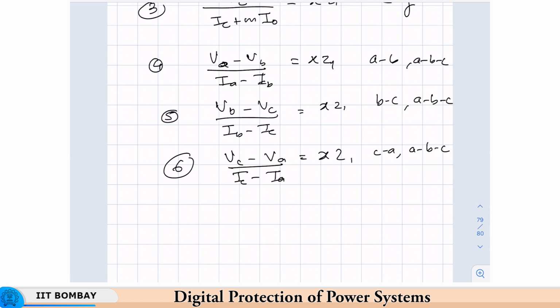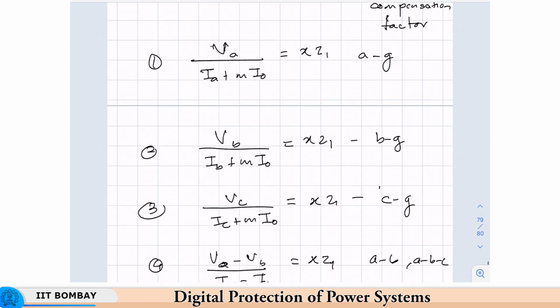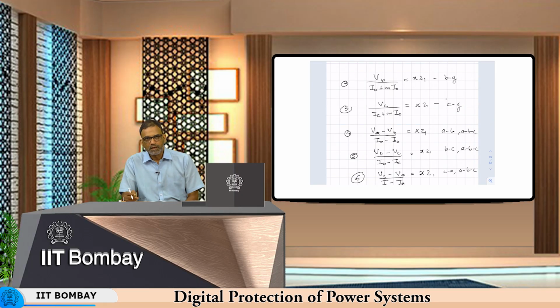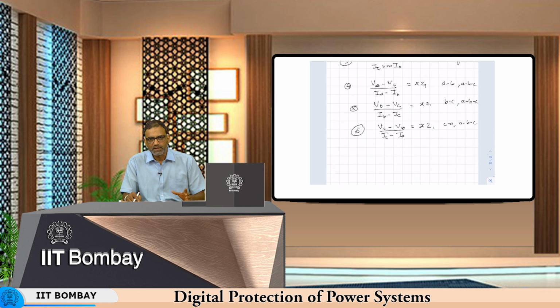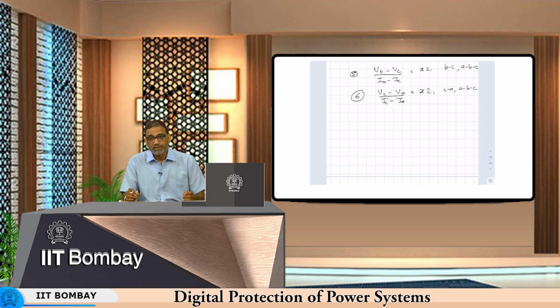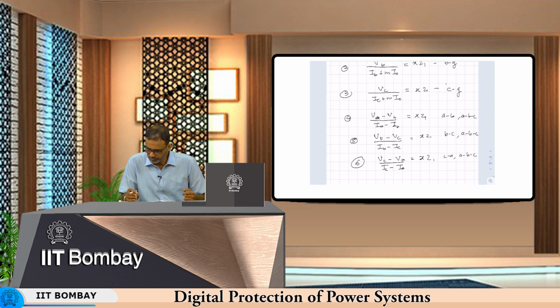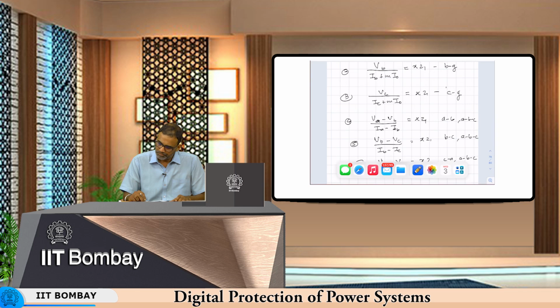Okay, so here you have to keep in mind that for cables, determining this M is a difficult task, because depending on where the fault occurs, the fault current may return through the sheath, through the armor, through the ground itself. And so this determination of this M or zero sequence compensation factor becomes a very difficult task. So setting of distance relays for cables is extremely difficult. Fortunately, the cable lengths are short, so important cables are protected mainly by differential protection rather than distance protection.